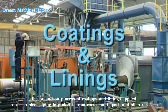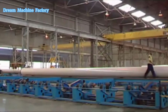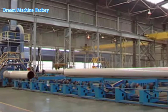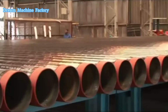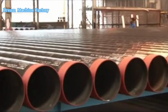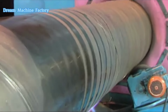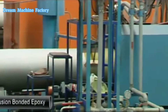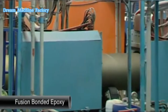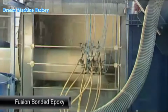Coatings and linings are protective layers applied to pipes, preventing corrosion, wear, and damage from environmental exposure and mechanical stresses. Carbon steel piping is frequently subjected to harsh environments where corrosion, impact, load, and soil stresses are common challenges. Fusion-bonded epoxy involves applying powdered epoxy, which is heated to form a durable, corrosion-resistant bond.